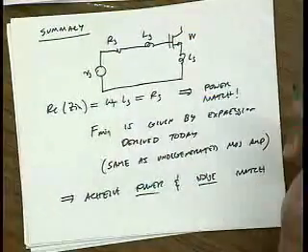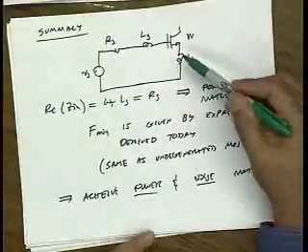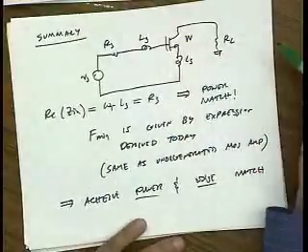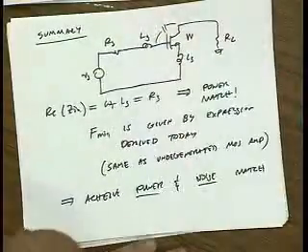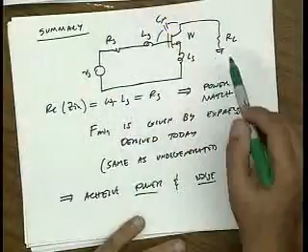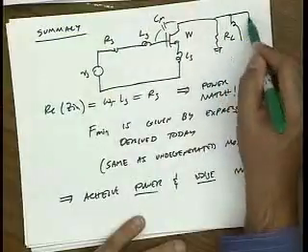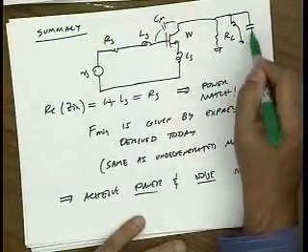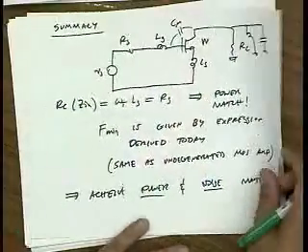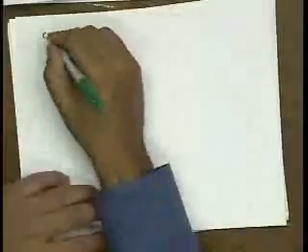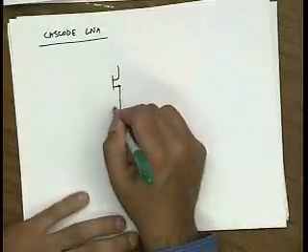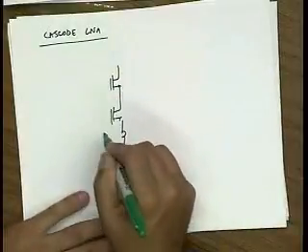Now, if you actually try to design one of these amplifiers, as I've shown here, let's say just driving a load, you'll find that it's actually quite a nightmare, because any real device has C mu, and C mu makes our device bilateral. And if I try to use a tuning network at the output to tune out the capacitance here, any change in the output load makes a change in the input load, and it gets very, very ugly. So almost everybody uses a cascode device. So again, same architecture, inductively degenerated.